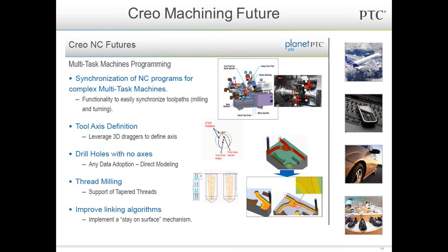One of the cool ones that you see on here that I like is this tool axis definition. And for any of you guys out there doing, well, I should say not 3 but 4 and 5 axis surfacing and trajectory stuff, when you want to go in and control an axis, usually what you have to have is an axis pointing in your Z direction, or essentially a long Z to control that, right? And wherever you want to, you could put 15 different axes that control it at different points and all kinds of other little stuff that you have.